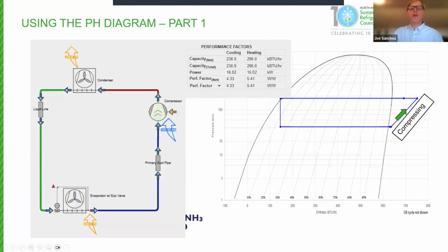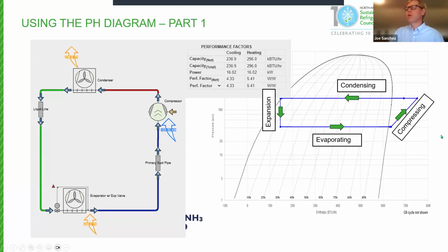Okay, so now that we have our refrigerants, we can start to walk through what the molecules are going through and what they're experiencing by putting this Carnot cycle overlaid on the map. So for example, the refrigerant is compressed, and then it passes through the vapor dome and it's condensed. Then it is expanded. Expansion is called isenthalpic, so it doesn't change any energy, it doesn't lose any energy. So you can see the enthalpy stays the same, and then evaporation to the right.